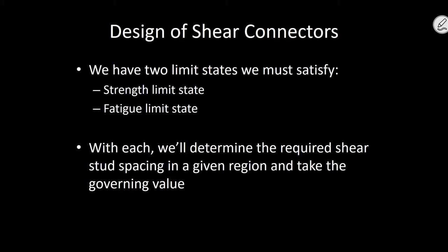Did you all do partially composite beams in steel? Did you all talk about partially composite beams in advanced steel? That's a topic in building design where we can actually say, you know what, I'm not going to provide the full amount of studs. I'm actually going to back it off a little bit, and your beam will still work. No way, shape, or form can we get away with that with bridges. Because of fatigue, it isn't going to matter.